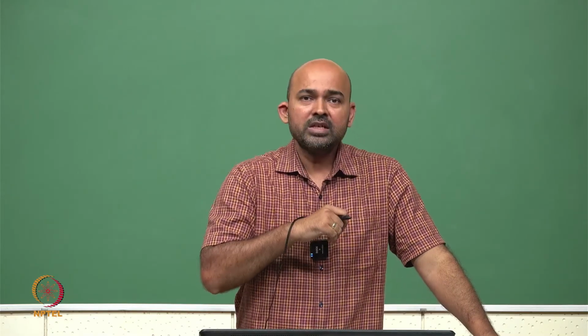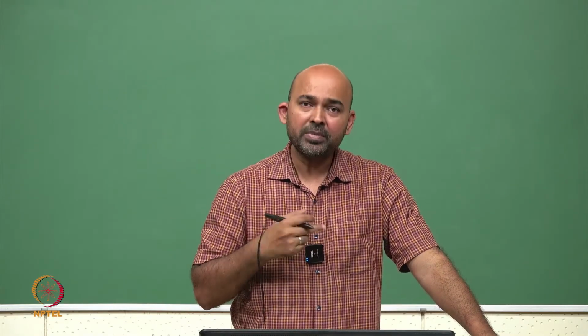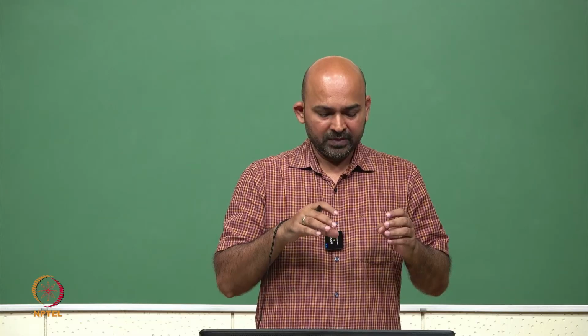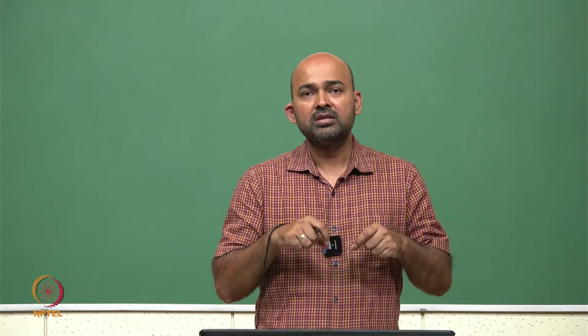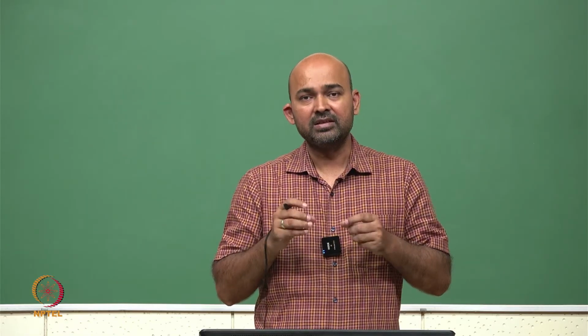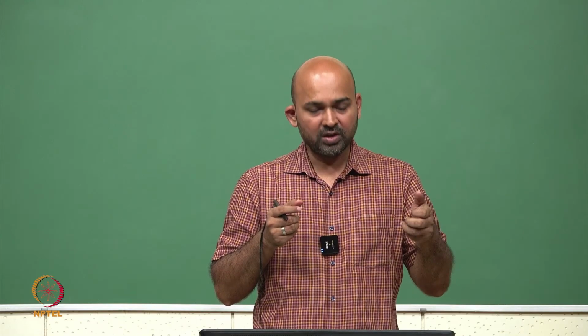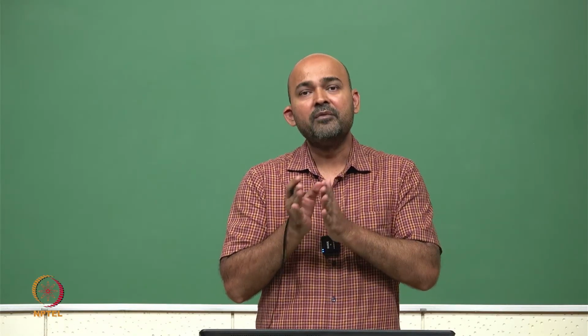In dynamic logic gates, we have a separate signal which is called clock. The function of this clock is that in dynamic logic gates we charge the load capacitance CL. CL is a capacitance. So we charge this CL capacitance using clock before every operation.